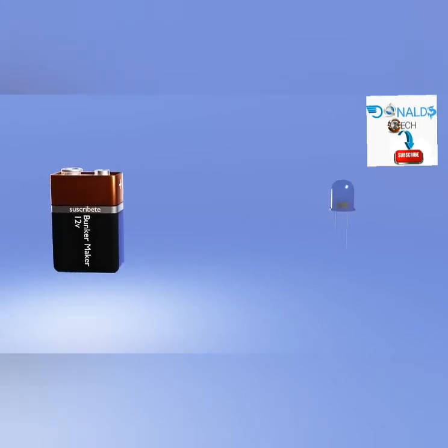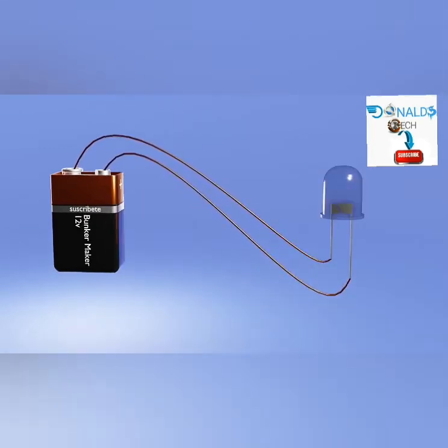At this point I think we are ready to start talking about what a resistor is for. The use of a resistor with a static value in a circuit allows us to regulate the voltage that will be generated in different components. Suppose we have a battery of 12 volts and a LED that works at a maximum of 3 volts. If it exceeds this value, it will burn. In this extremely simple circuit, just by putting a resistor of the right value, we can make exactly 3 volts